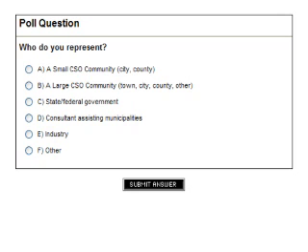While we're waiting, we do have several questions, and I'm going to start with the first one. I believe it would be directed to Mark, since Mark talked about tunnels. The question is, what is the possibility of leakage from the tunnel itself to the ground, therefore adversely affecting groundwater? In Atlanta, they're fortunate to have good solid bedrock of granite, and the tunnel is 200-300 feet deep. The only groundwater in that part of the country is really through fissures in the rock itself. So groundwater contamination is not a problem in that tunnel system.